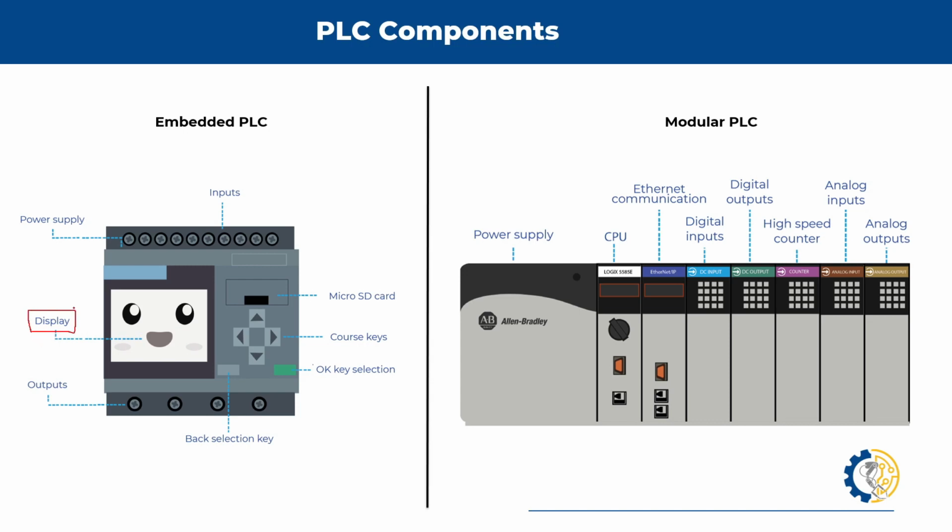Now, the display for embedded PLCs. Here we have our PLC, and this is its display. Now, what is this for? To view what we're programming. The embedded PLCs can be programmed without the need of software or a computer. We can start programming and adding the instructions through our display.